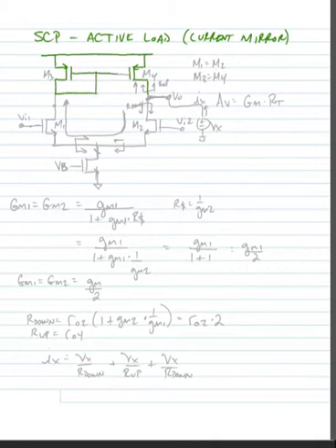We're going to make a PMOS current source, a current mirror, and we're going to tie it to an NMOS differential source coupled pair input. Rather than biasing this transistor with an ideal current source, we're going to use an NMOS current source that's just tied to a DC bias, setting up our desired output current.